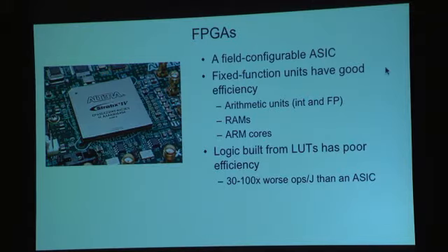Instead, if somebody has a piece of hardware they want to prototype, they'll build it on a field programmable gate array, an FPGA. And there's good news and bad news about FPGAs. The good news is that they have a bunch of fixed function logic on them. In the early days, in the old 4000 series Xilinx parts that came out in the 1980s, I was a professor at MIT at the time, and I converted our undergraduate logic design course to use FPGAs. And all you got on the FPGAs were what were called LUTs, lookup tables. So you could implement random logic using four input arbitrary function gates.